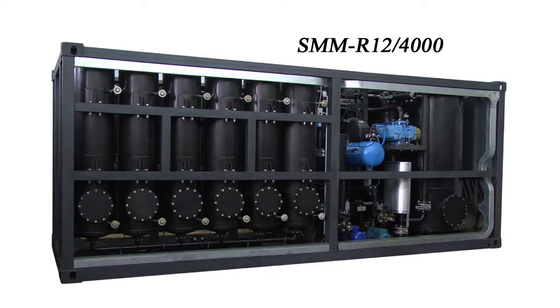As an alternative to the existing oil regeneration process, GlobeCore offers equipment based on percolation regeneration of transformer oils with Fuller's earth. This technology has the following advantages as compared to the existing ones. After regeneration, physical and chemical parameters of the oil, such as tangent delta and acidity, exceed those of fresh oil.